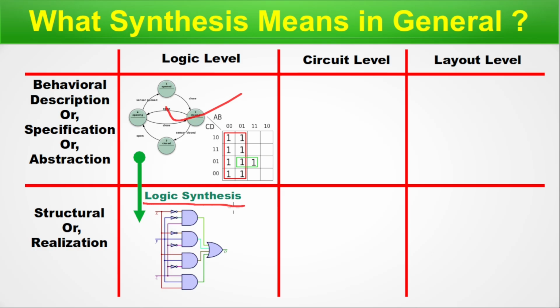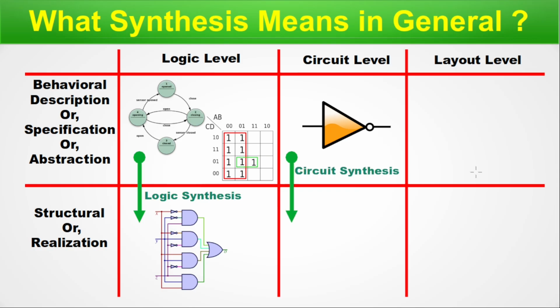That means the VLSI design automation. Whatever code you have written is now entering the first step where it connects to the standard cell library, which is certified by the foundry and is realizable in silicon. Now let us move on to the circuit level, in case you are entering as a circuit designer. So we have our logic gates. It's a different notation. Why I have kept this inverter, you will see in the upcoming infographics. Now, when we want to convert this into a structural part, we go through the circuit synthesis process. In that case, we transfer this logic gate into transistors.